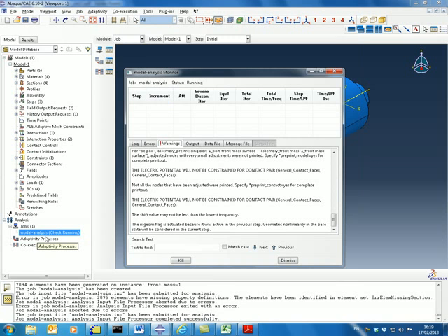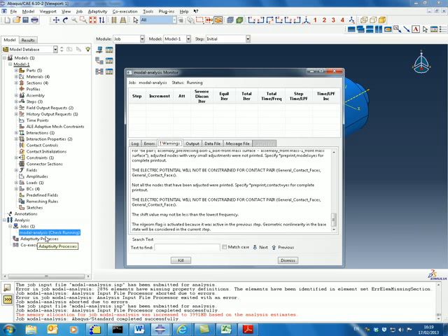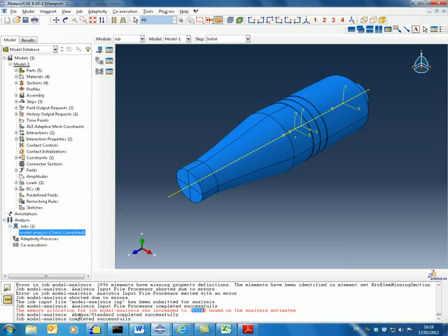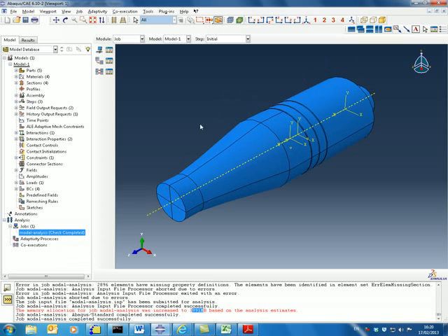Although the checking could take time to be completed, I would strongly recommend to go through and check your file before you run it on the server. As you can see, the required RAM has also increased because of the size of the file, and it's completed, so it can be run now successfully. I'll show you the result in the next video for the modal analysis, and then continue to the harmonic analysis.